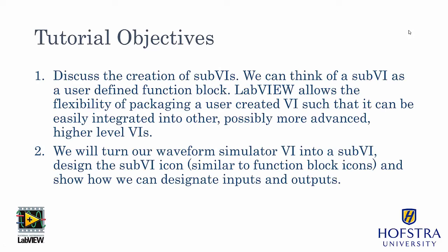Today we're going to discuss the creation of SubVIs. You can think of a SubVI as a user-defined function block. LabVIEW allows the flexibility of packaging a user-created VI such that it can be easily integrated into other, possibly more advanced, higher-level VIs. We will turn our waveform simulator VI into a SubVI, design the SubVI icon, similar to function block icons, and show how we can designate inputs and outputs.